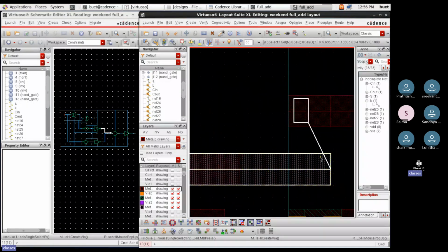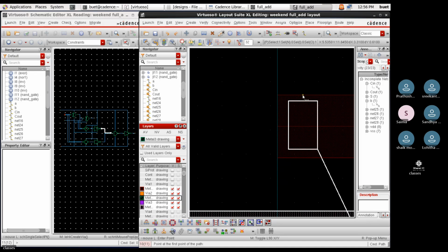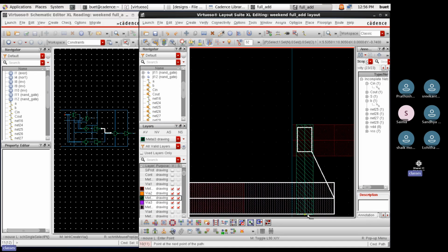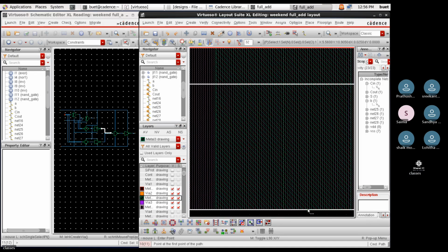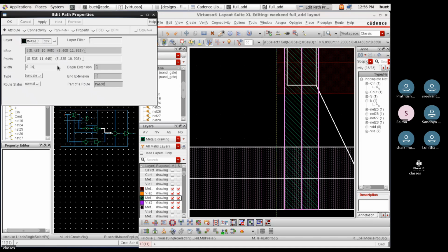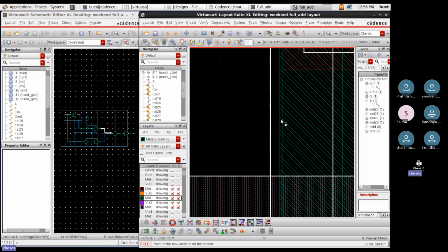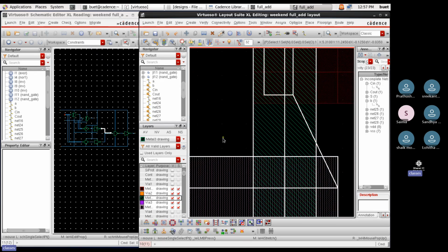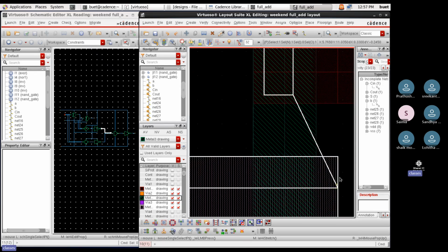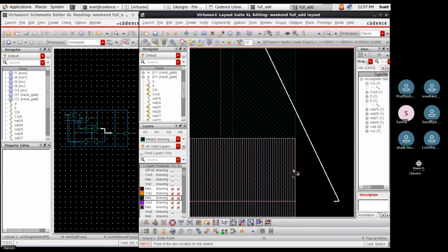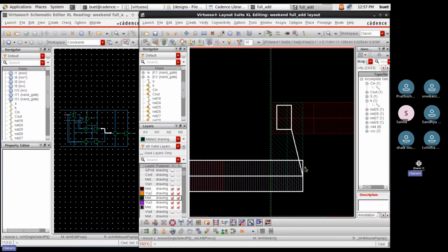And here again I will take an M3 metal, simply I will take an M3 metal here. To 6, and I will simply make it aligned up till this level. Okay, and I will pull this one back. No extra hanging metal should be there.